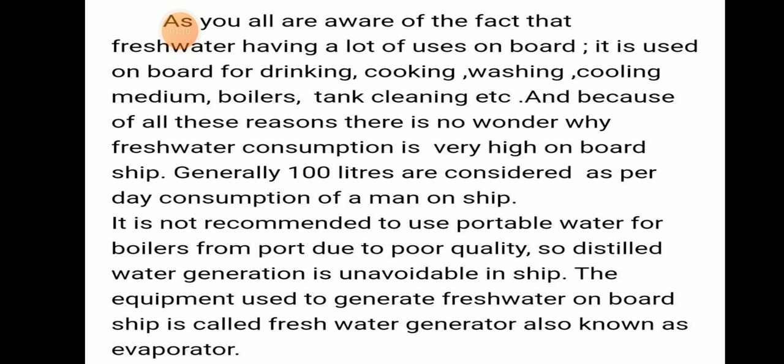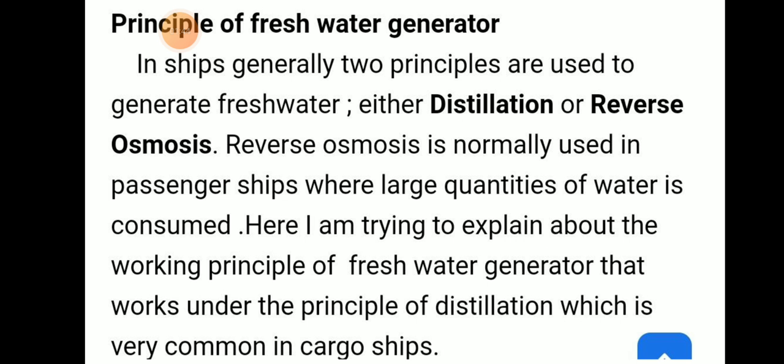We use fresh water on board ship for many purposes like drinking, cooking, washing, cooling medium, boilers, tank cleaning, etc. Because of all these reasons, freshwater consumption is very high on board. Generally 100 liters per day is considered the consumption of a man on ship. It is not recommended to use potable water from port for boilers due to poor quality, so distilled water generation is unavoidable. The equipment used to generate fresh water is called a freshwater generator, also known as an evaporator.